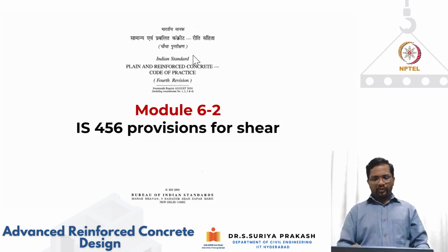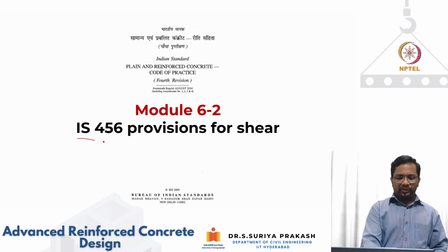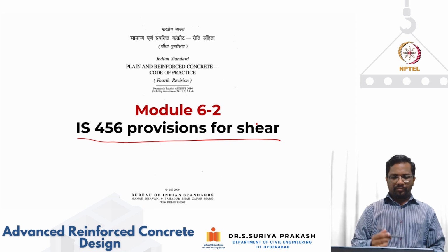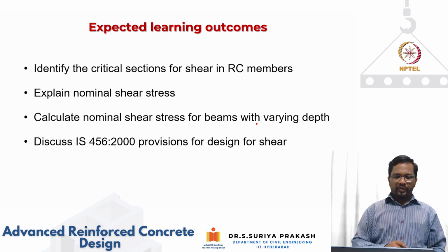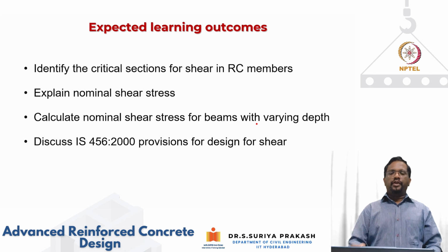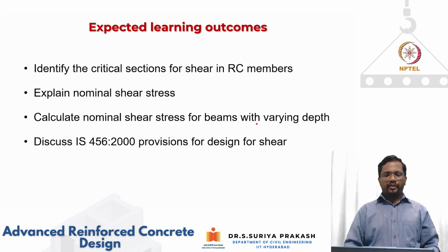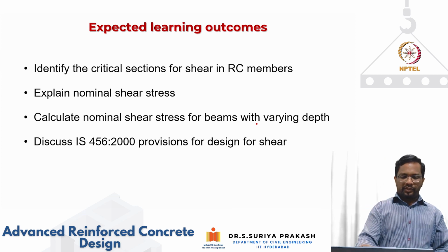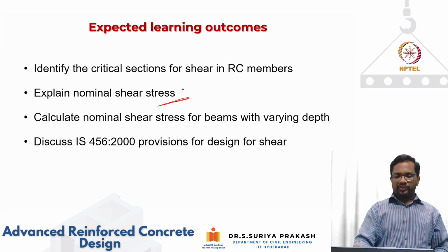Right. So we are following this IS 456 provisions for shear, and you know that IS 456 2000 is the code of practice for plain and reinforced concrete design in India. And so the expected learning outcomes from this part of the video is students should be able to identify the critical sections for shear for the design of RC members, and should be able to explain what is nominal shear stress and how to calculate nominal shear stress for beams with varying depth.